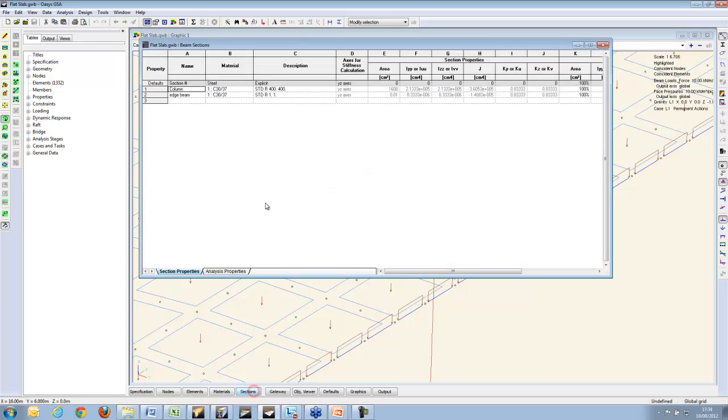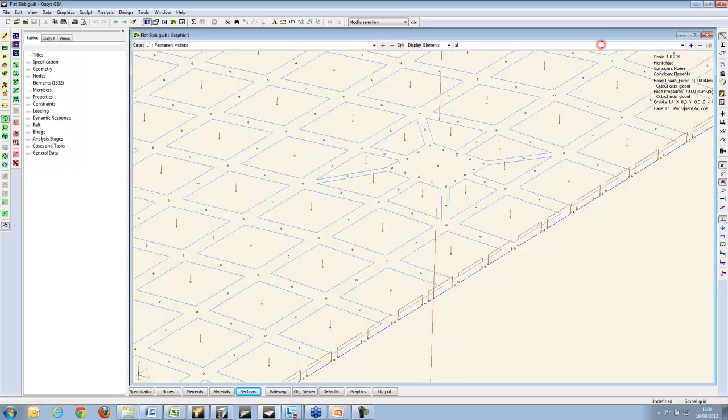These bars have negligible cross-section. Of course, being bars, they have no bending stiffness, but this means they're quite suitable for applying a UDL onto, which then distributes onto the slab, and their section is such that they don't contribute stiffness, or at least not stiffness that you'd notice to the overall analysis.